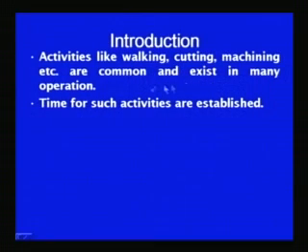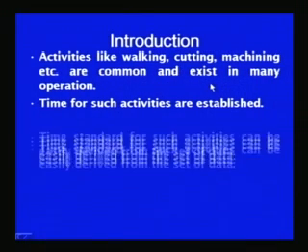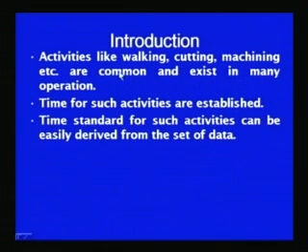The standard data method is another method which is commonly used for establishing the time required to carry out the job. There are various activities which are very frequently carried out in the industry, like walking, cutting, machining, and if the time values are available for these simple activities, then the time values required for other operations in which these activities are carried out can be obtained from the already established time values.